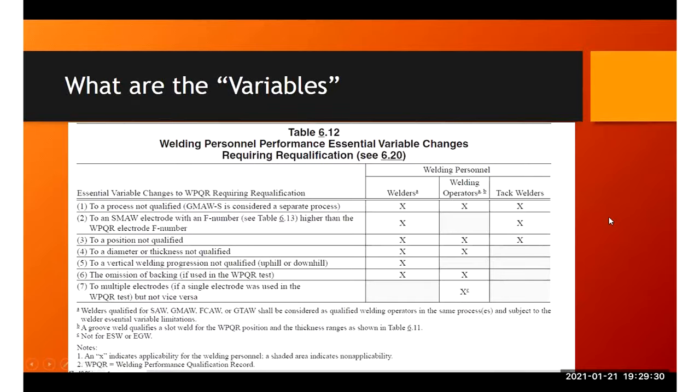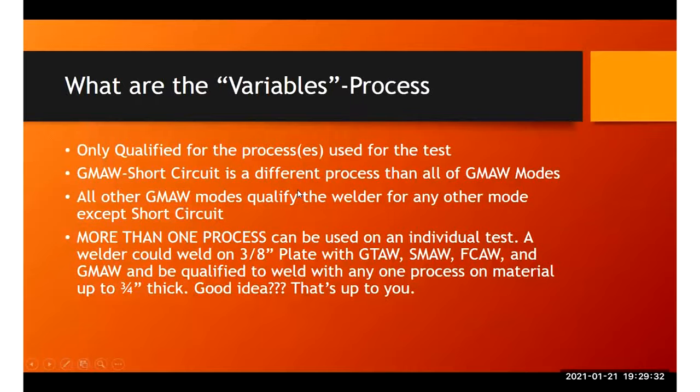So we'll go through the first one, the process. Okay, it's only qualified for the processes used for the test. And again, GMAW short circuit is a different process than all of the other GMAW modes. But always remember, all the other modes do overlap.